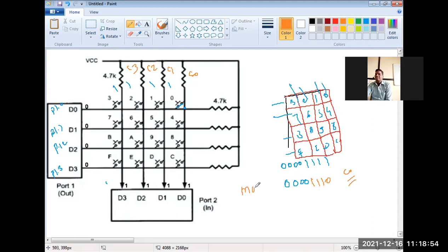So I take this data into the accumulator and mask the accumulator value with all ones, so I can say which key is pressed. When you mask that, the value indicates 1 at this moment, which means there is a change in that variable. So I sense that C0 is pressed, and I transfer that, meaning the 0 button is pressed.